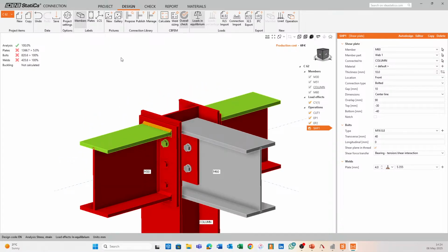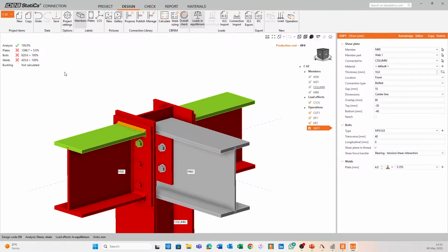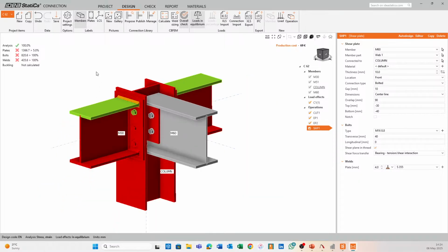Right, so I know that there are engineers that will limit themselves to 1.5% plastic strain, and you can actually set up the program to stop at 1.5% plastic strain, or you can even set it to 0%, which means that the yield strength of the material will be the failing criteria. All right, but we're sitting at 1,366.7% plastic strain, which is absolutely horrifying.